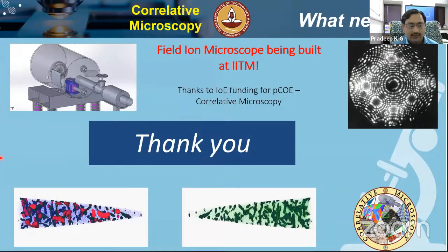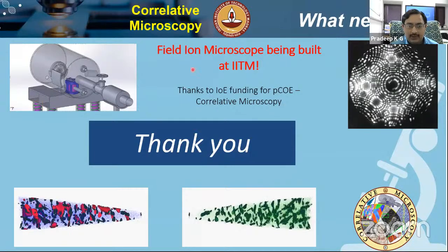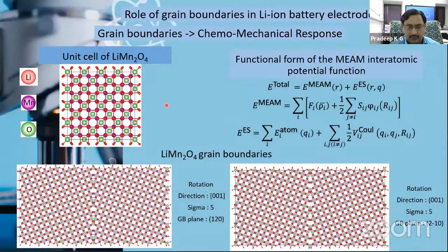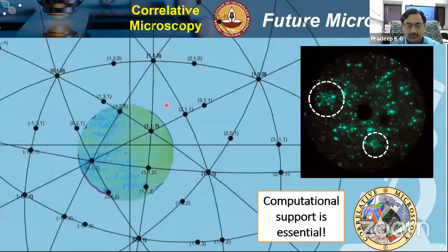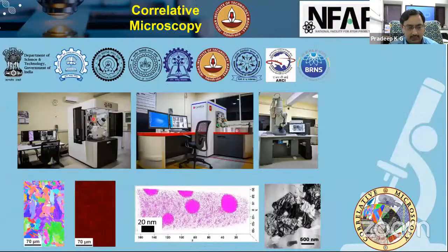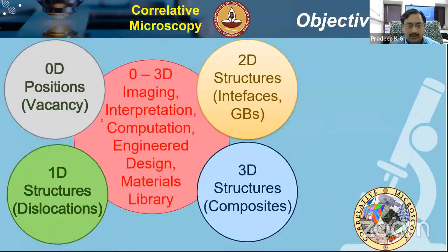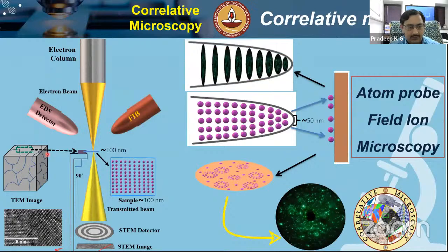So it's not just that we try to image them. Probably I'll see if we can go back to this. We can even look into these materials in the cross section in all three directions. We have this dual beam microscope where you can get this kind of surface imaging, and then you can have this focused ion beam as I just showed in the earlier schematic. So the bulk surface can be imaged, then we can do a serial cross-sectioning across the surfaces of the regions of interest using this focused ion beam. That means for each slicing that we do, we start to see their cross-sectional microstructure also.